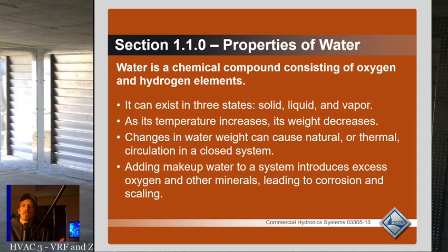The changes in the water weight, the changes in the weight of the fluid, is what causes circulation in a system, or causes that air to rise. Same thing with the flue. Our 80% and lower equipment, the flue gets vented out of the chimney because the warm air tends to rise. The warm flue gas tends to rise up through the flue and up through the chimney, and that causes a stack effect, right? So the warm fluids rise, but heat does not rise.